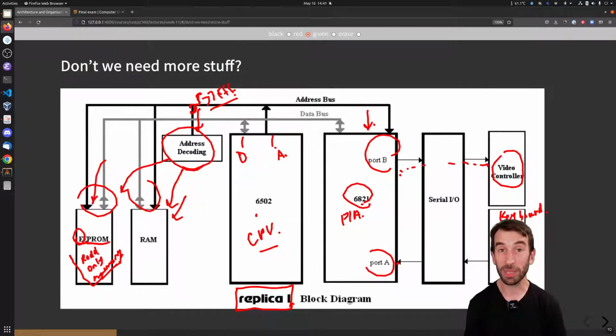So I can erase it with the UV light, and then I have to use what's called a ROM programmer, which is another physical device that you have to use special voltages to set up all of the memory cells to a certain state, and then it can be read by my CPU at regular voltages. I'm not quite sure how that stuff works.